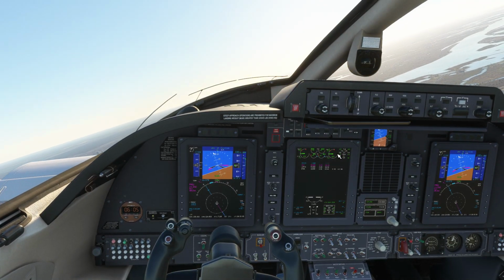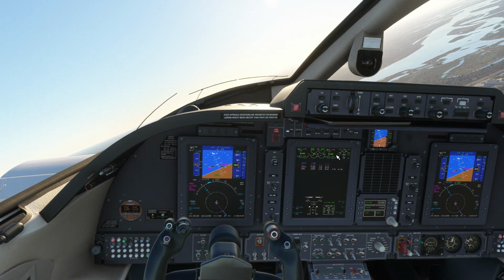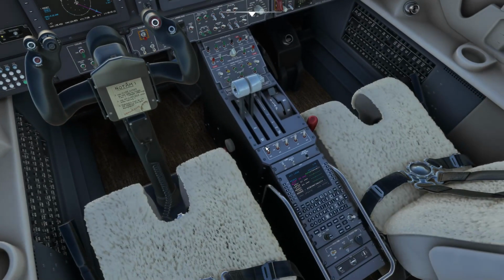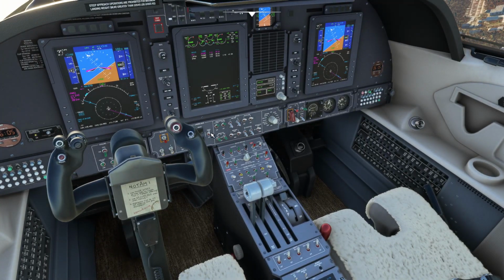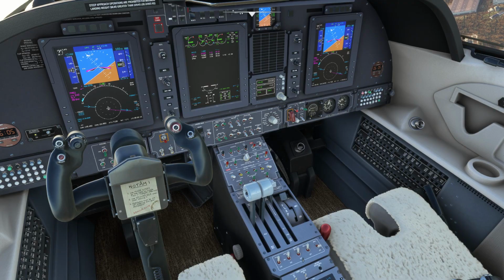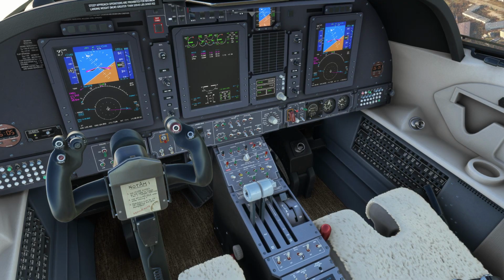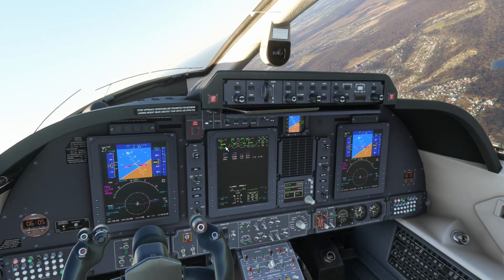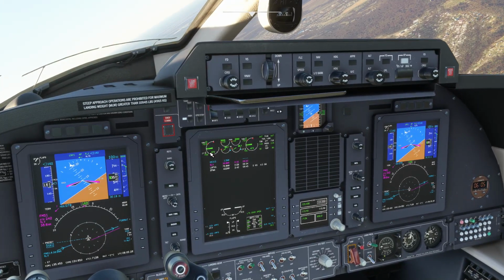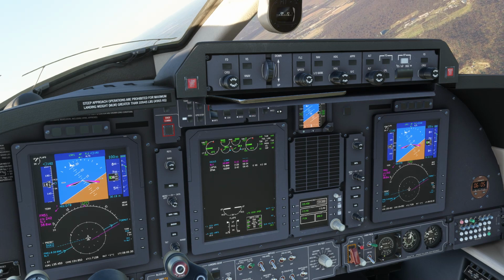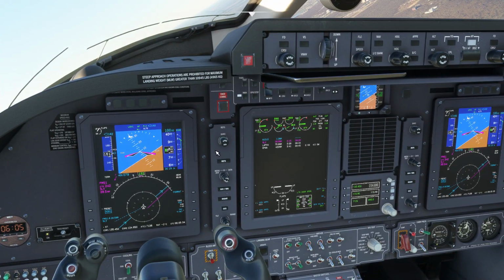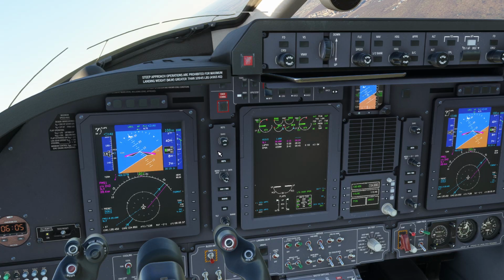Rescuer 112. Right. So after takeoff, flaps are up. Can we see them up? Yep. And that's up. Landing lights are on. Wing and recognition are off. Condition levers stay where they are. Climb power is set. That's here. We can adjust it slightly. Passenger signs, we will leave them on. Pressurization is check.